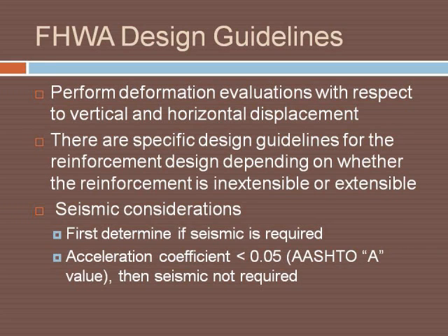Also, we need to consider if earthquake should be considered, and to determine that, you look at the acceleration coefficient. FHWA recommends that if the acceleration coefficient is less than 0.05, then the seismic analysis is not required.